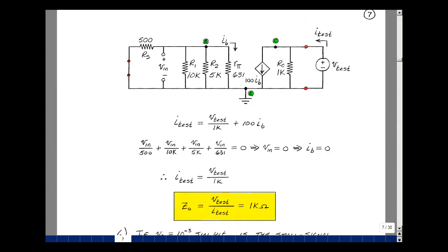As we showed in ECE301 and 202, to find the Thevenin equivalent circuit, you remove the load, that was R sub L here, set all independent sources equal to 0, that's what was over here, and then find the resistance looking back in. This is a dependent source, and so we're going to leave it there. Looking back in here, we have a resistor, but we also have this controlled source, and this is not a resistor, but is a relationship.